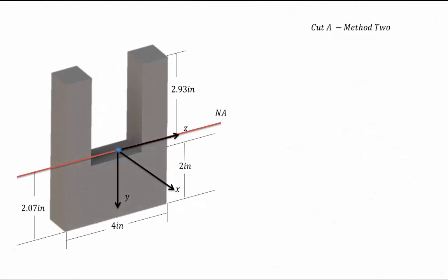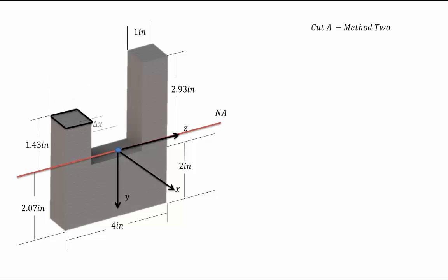Okay, so here's our section as we saw in the previous slide. However, we're going to look at the cut from the other direction this time. As before, tau xy is running down the face of the shape, but tau yx is in the opposite direction, but this is only to maintain equilibrium. For convention, Q will be negative above the neutral axis and positive below the neutral axis. We're going to use x equilibrium to solve for the shear stress on this section.